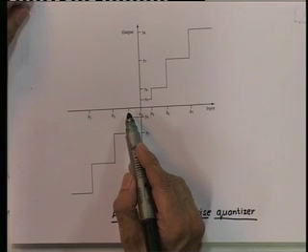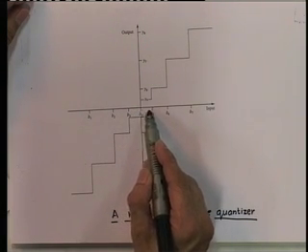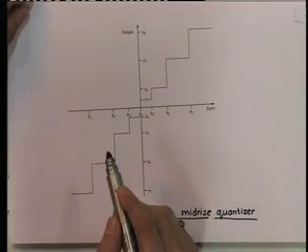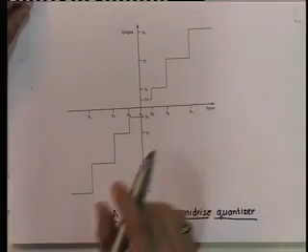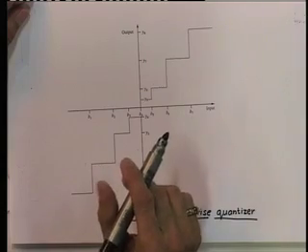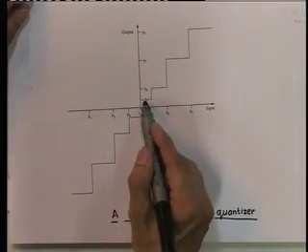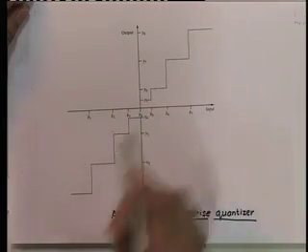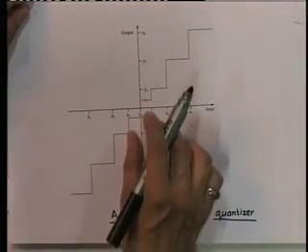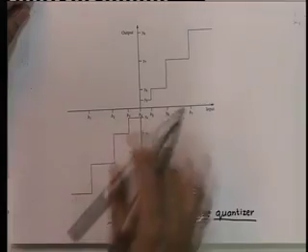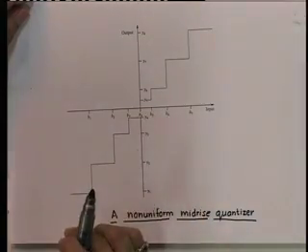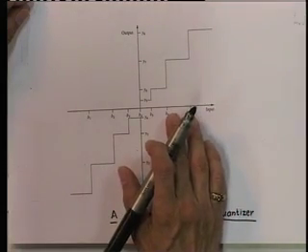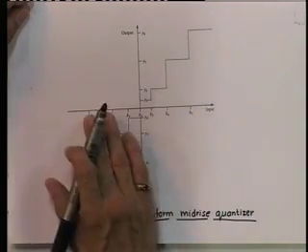Notice that the intervals closer to 0 are smaller, hence the maximum value that the quantizer error can take is also smaller in this region, and that is why there is a better approximation. Now, we pay for this improvement in accuracy at lower input levels by incurring larger errors when the input falls in the outer intervals.